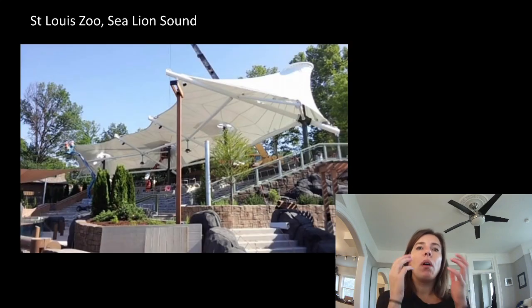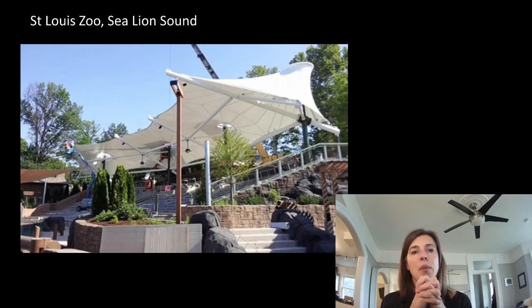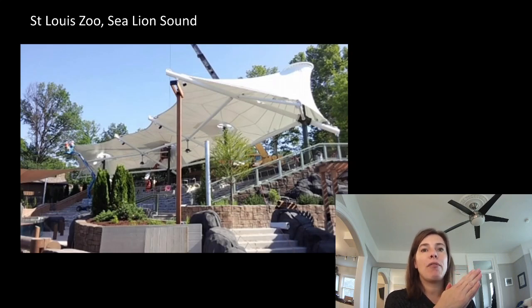So there's the overall structure, or the overall built work that needs to be represented, but it gets even more interesting with fabric objects for a few different reasons. Because when we're doing fabric and cable elements, we pre-stress things. So we need to know what length things need to be in the shop and what length they need to be in their final form.